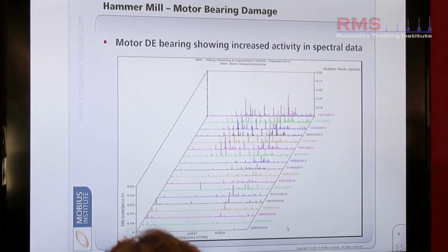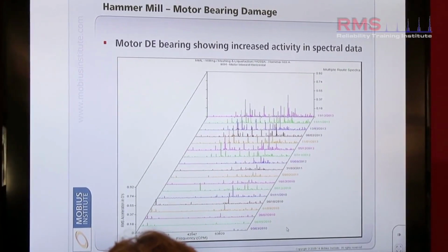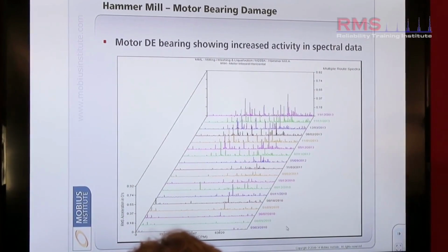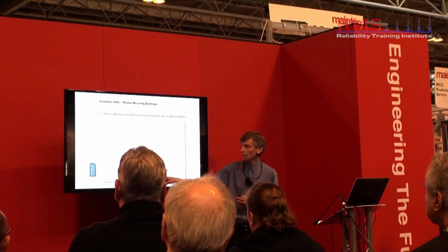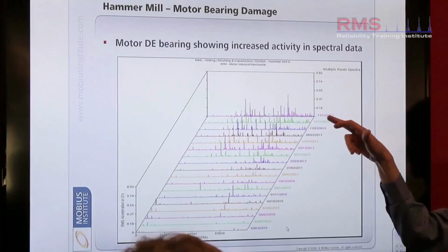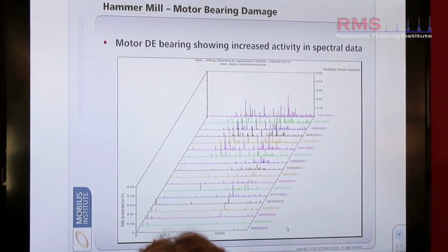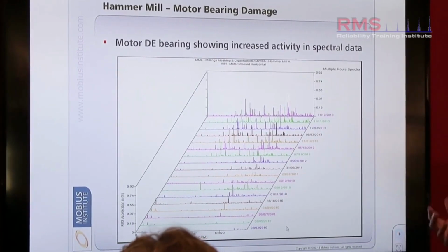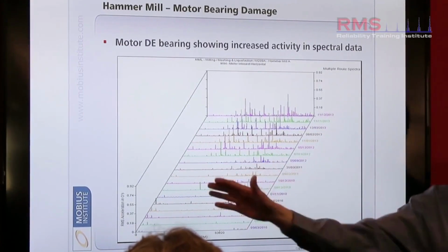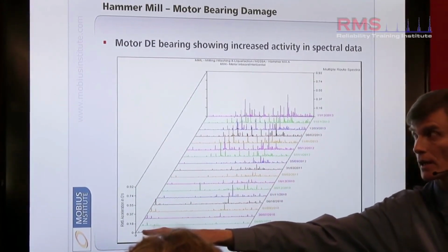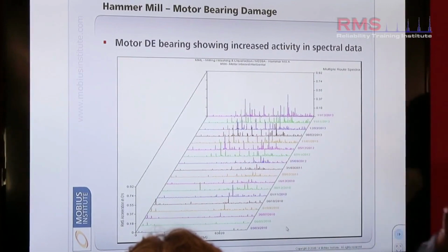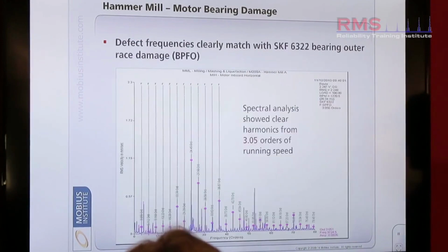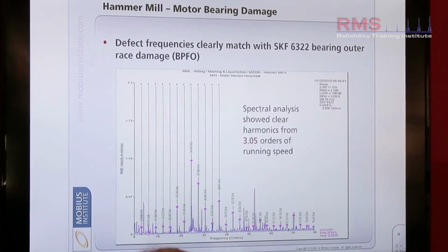What's this? Well, this is the frequency heartbeat of a particular point on the machine, the motor drive end or motor inboard bearing. So this is the bearing at the motor drive end. And you can see the heartbeat month on month here, the most recent reading back when the problem was present, and how the heartbeat has changed. If this was a problem with balance, for example, that would be lower down the scale. My 1x peak is this very small peak down here, not of concern. But these stronger peaks here are the main cause of that trend of degradation.